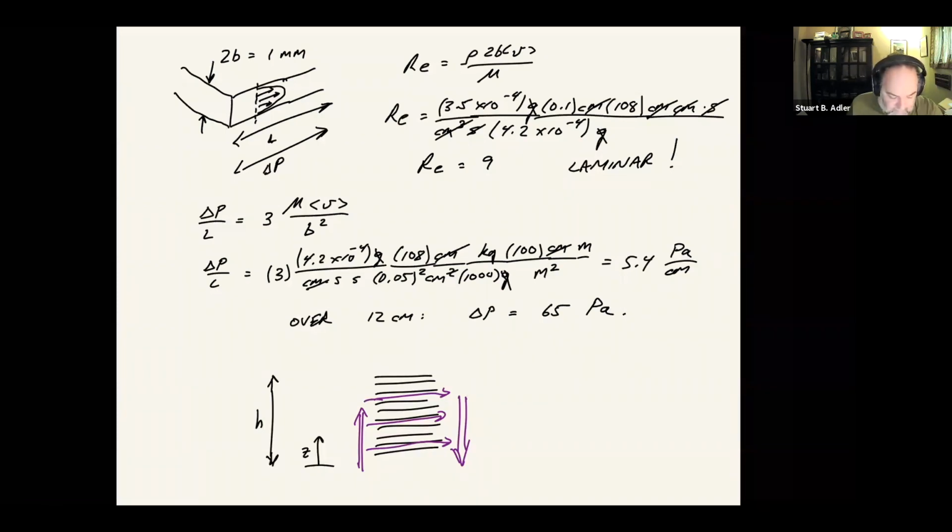Maybe we can tolerate some variation in airflow, but remember, airflow is tied to cooling, and cooling is tied to temperature. We've assumed we can get a certain airflow in order to maintain the temperature of the stack locally. If we have more airflow at the bottom because the pressure drop is bigger, then that could lead to maldistribution of the air and thus a non-uniform cooling in the stack.